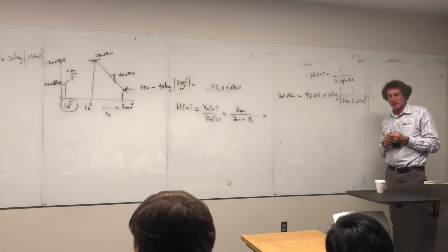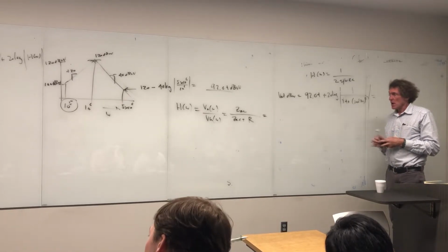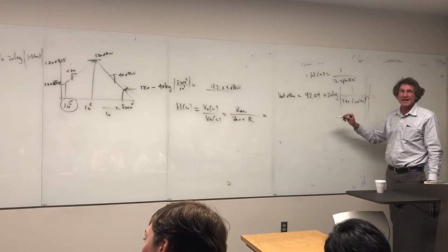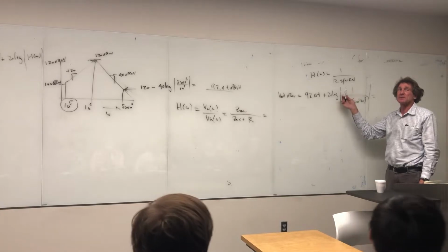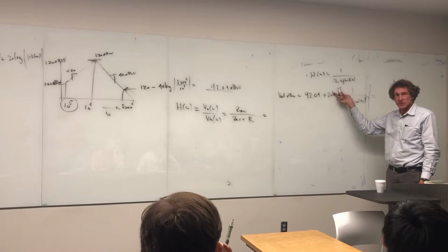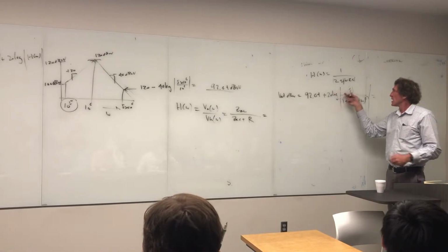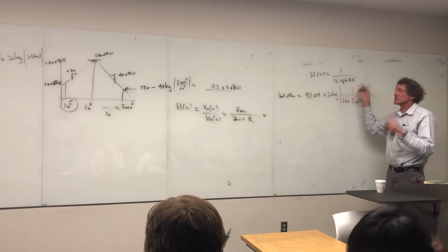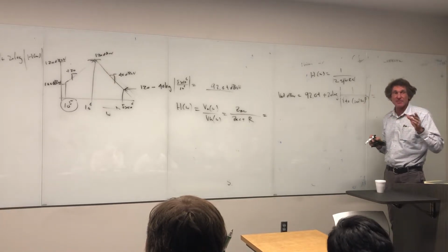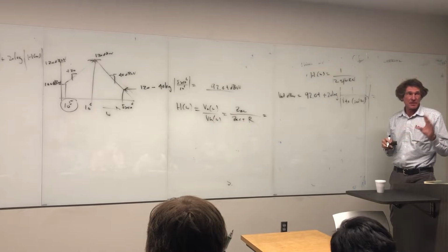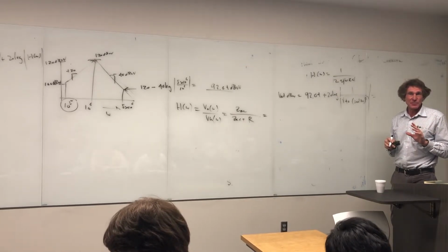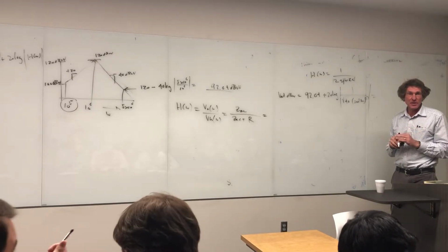Why do you have the square root? All right, what we have to do is take the magnitude of this, right? Well, the magnitude of a plus jb is the square root of a squared plus b squared, right? A in this case is 2. Square that, you get 4. Then I have plus omega RC squared, square root of it, because it's a magnitude of a real plus an imaginary. You have to remember magnitude, okay? Anything else about this one? You good on that?